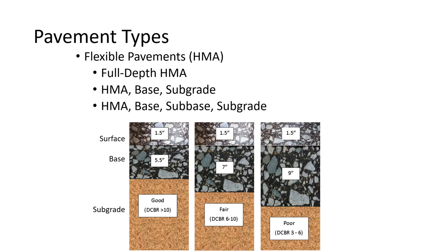They've changed their design format since then. It's a lot more dynamic now, and we've ended up with, sometimes, half the pavement depth we used to have on the projects. And we did a project in early 2012, 2013, right about the time they switched that system, and we literally ended up with half the pavement we thought we were going to need based on the original INDOT specifications.